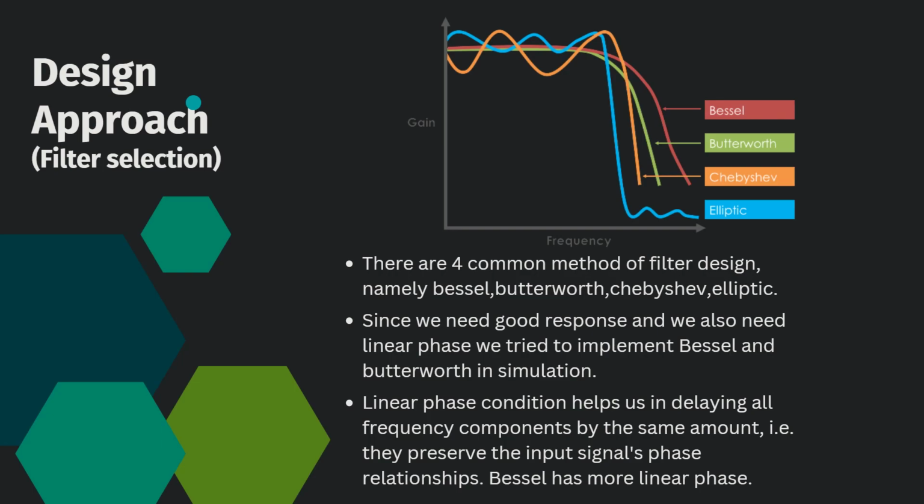As we see, the calculations are based on the second order low pass filter. For every filter there would be a coefficient, so we chose the Butterworth coefficients of the second order low pass filter and used them in the calculations. As you see, A1 and B1 are the coefficients here, which are standardized. So we can't directly change any resistance values manually because that would affect the circuit and the coefficients. And for every circuit we made the same calculations.